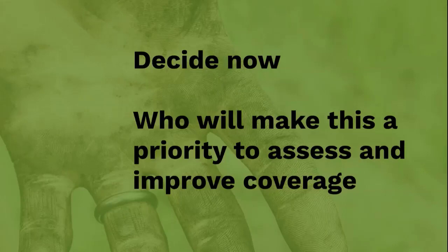Okay, now you know the importance of air. Decide now who will optimize your sprayers and look for proper air volume. Mismatched air is the primary culprit for drift and poor coverage. In this next set of slides, you will see more specific ways on how to adjust air.